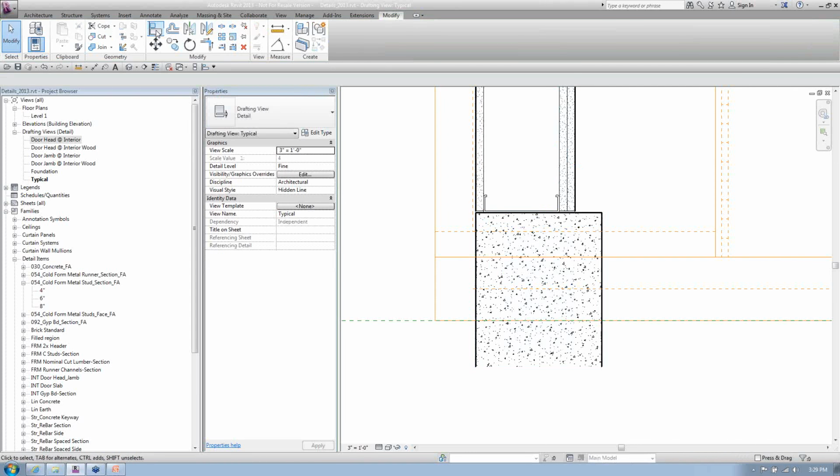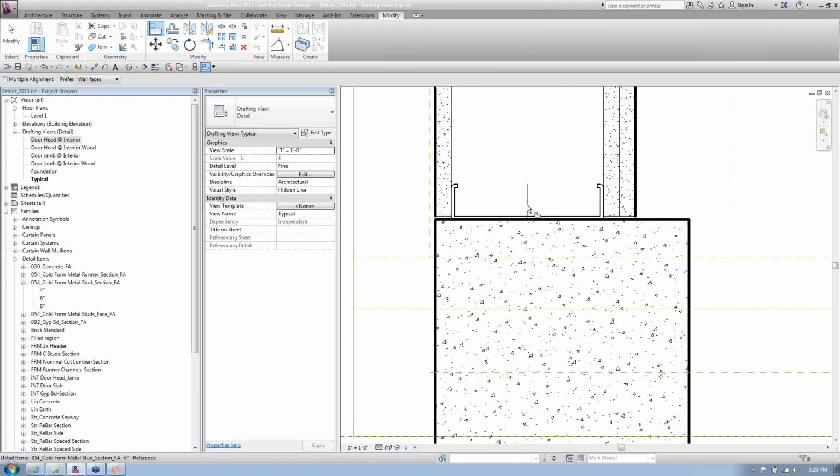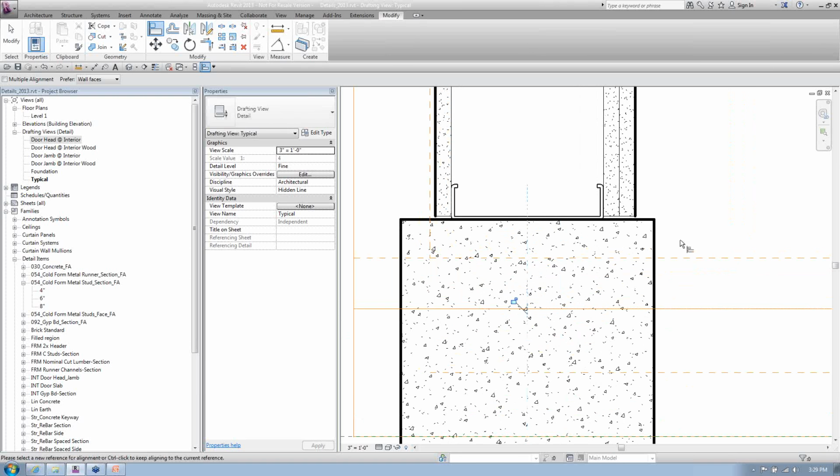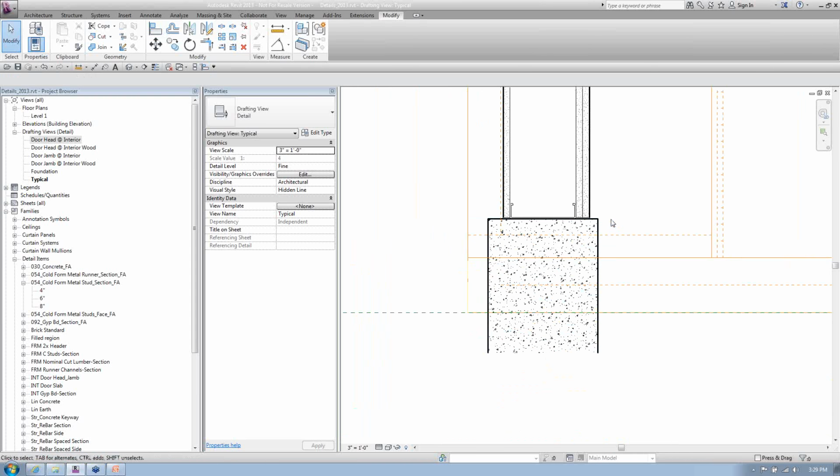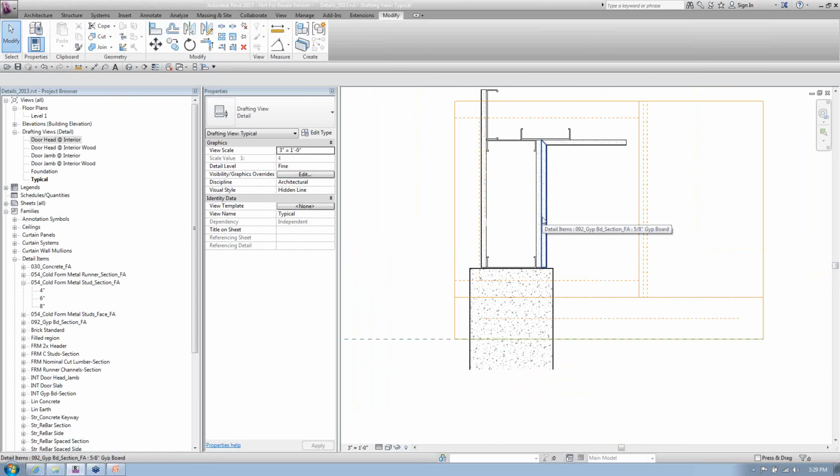And maybe it was supposed to be centered, so you'll also see that all the components I create, even though I don't really need a center point of this metal stud, I put it in there as I go through these, because that way I can now align and get these things centered on an as-needed basis as I go through and set this up. So for me, all the components I'm creating always have a center reference to them, for reasons of aligning, locking, constraining, and doing things like that as we go through and set this up.